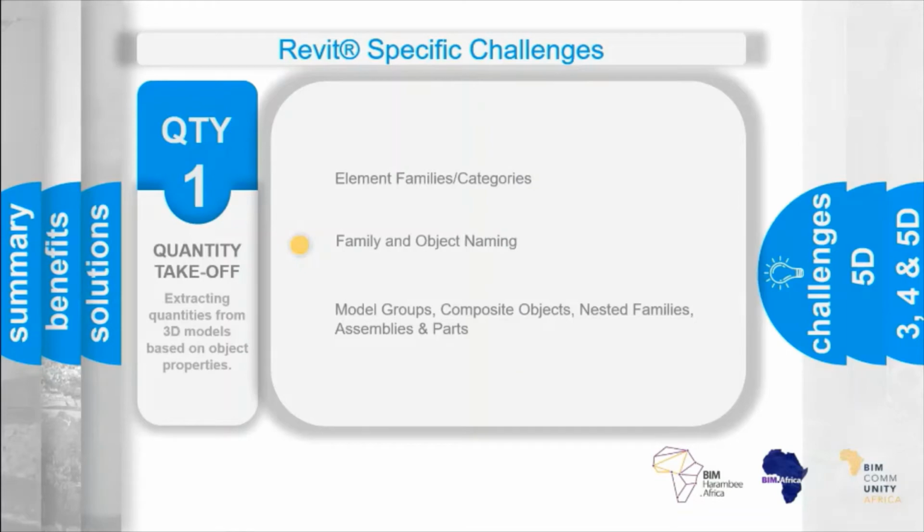We're speaking to our software vendors and our takeoff and estimating vendors so that we can try and build formulas that build up descriptions for estimates based on the object properties, not necessarily based on the type name. And what we can then do is see if there's a mismatch between what the object properties are telling us and what the type name is telling us. And we can raise that as a flag so that the model author can correct it, hopefully improving model data quality. But again, there are issues and challenges if the model objects aren't correctly populated.